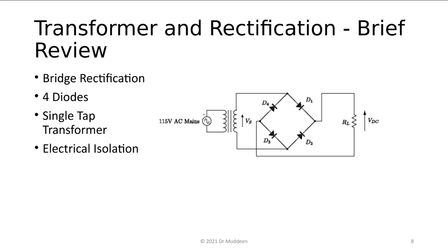Now, just a general comment on that. When you go into the lab and in your power labs and so on, you would have come across a device called an auto transformer. An auto transformer is one where the secondary coil is actually part of the primary. So there's no electrical isolation between the secondary and the primary. It works as a step down. It's like a big variable resistor, except that it's a transformer coil that you're dealing with.